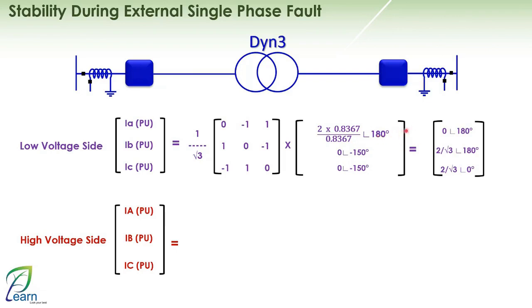So, where is the effect of the vector group, which is an angle of negative 90? It's not present. You have a single phase, right? And thus, this is the final result. If you multiply this matrix by this matrix, you will find this as the final result. Wow, now here, the fault is on phase A, and despite that, I found here 0 in A, and phases B and C are the ones that have currents.